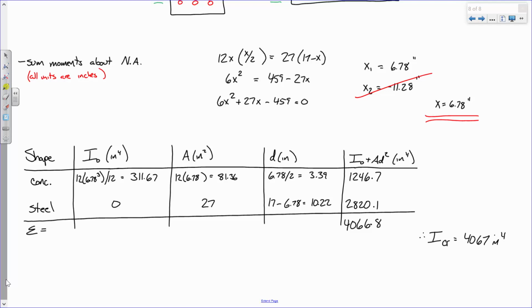So you're going to have a beam that in all actuality kind of looks like this. You know, like this is the beam that's uncracked and this is the beam that's cracked. So later on, we're going to have to compute sort of an effective moment of inertia that represents the fact that some of the beam's cracked and some of it isn't. We don't have to worry about that now, but that'll become important when we try and make sure that the beams don't deflect too much, because some of the beam's cracked and some of it isn't, so our deflection limit has to use the right moment of inertia. Does that make sense? Everybody okay with that? Okay. All right.